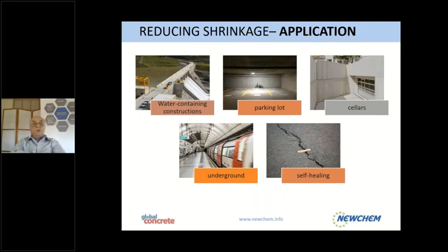The steel will hold the cracked concrete together. But if the concrete doesn't crack, then you can start to replace a part of the steel. And 1 ton of steel is producing about 1.6 tons of CO2. That means if you reduce your rebars in concrete, you will also reduce your CO2 emission to the air.